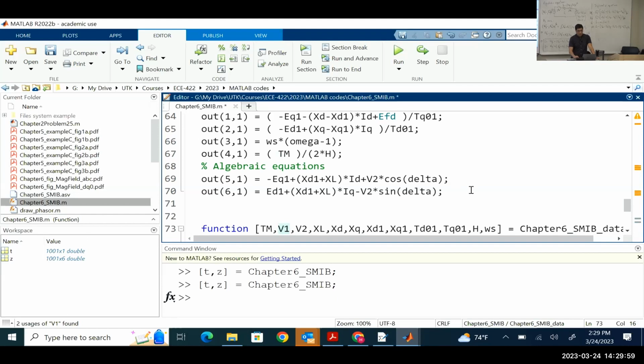What happened with this variable now? We need to consider now that you have here a short circuit. If you have a short circuit, these reactances will not get involved with the current. And the same thing with the voltage. So in the equation, we need to get rid of the reactance of the line and voltage V2. So we're going to modify this.